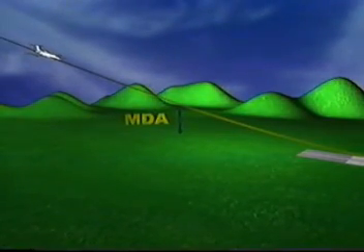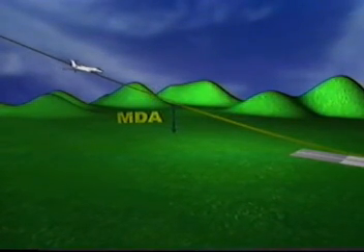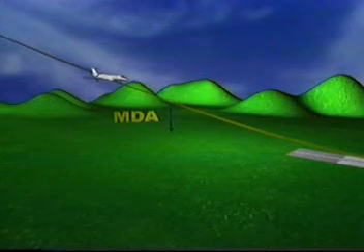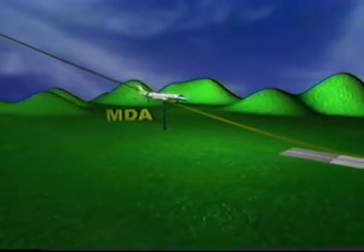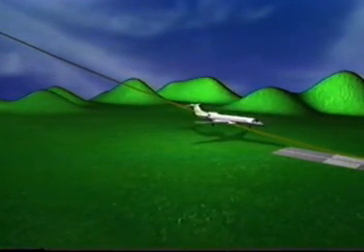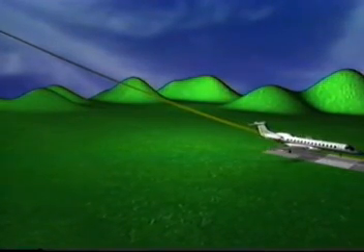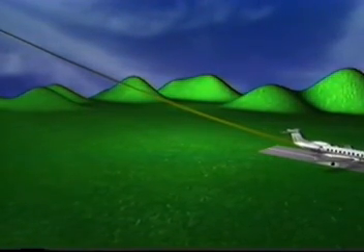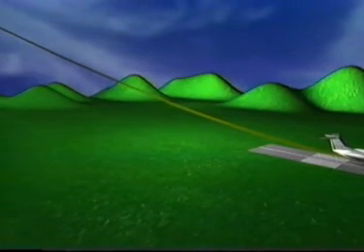With radio navigation equipment available these days, a descent path can be created with which the aircraft descends to reach the MDA at a point where, if the runway is in sight, the descent can be continued without interruption on a normal glide path towards the touchdown point. We do not mean to invent new types of approaches. What we mean is a more efficient and safer use of existing approach procedure.